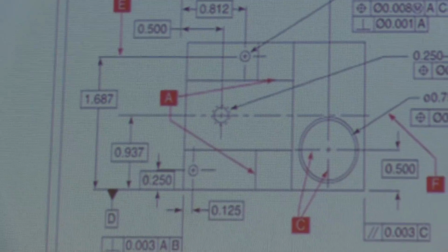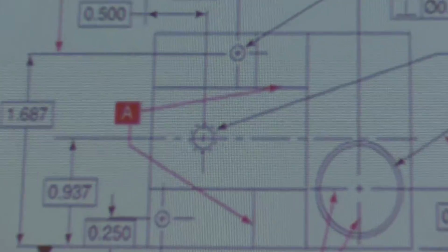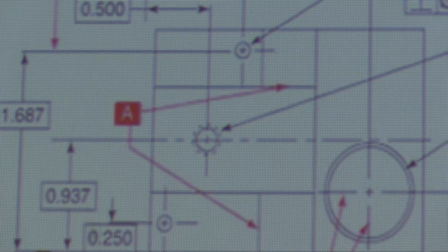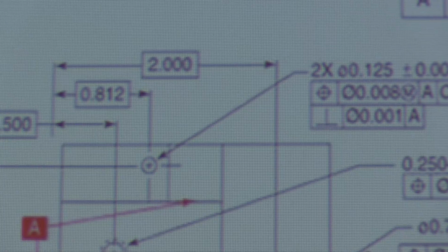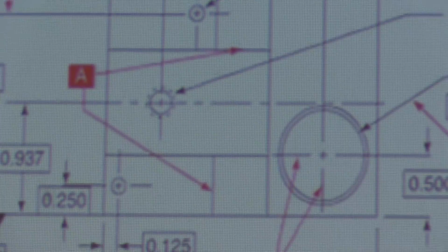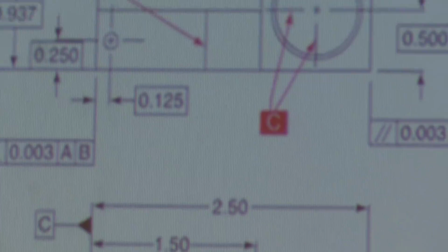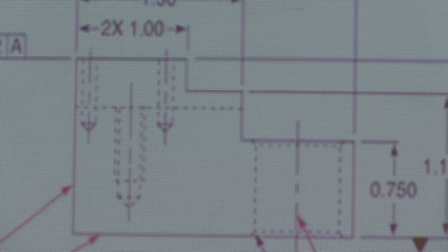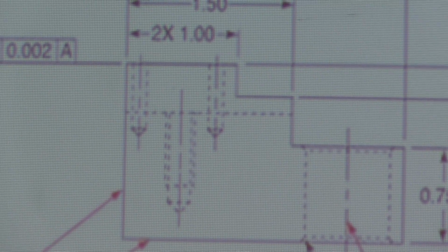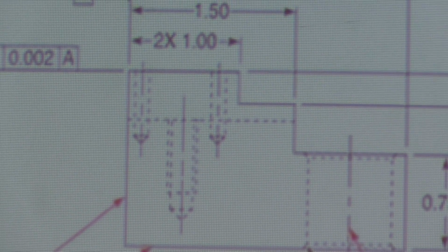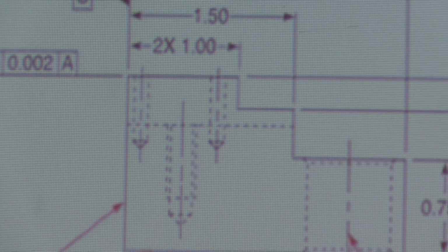Another example up here, you can see the 3 small holes on the top view. Your top one there, middle, left-hand view. Down here are hidden lines on the left-hand side, showing the 3 different representations of holes as well.